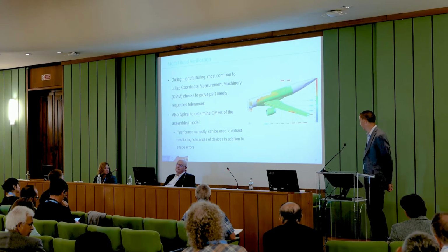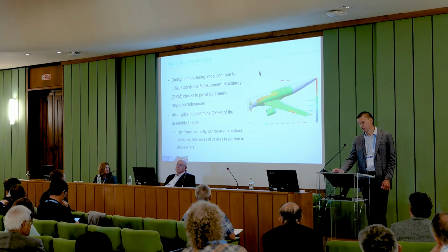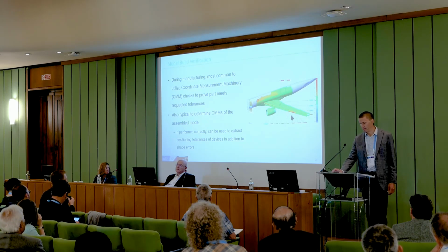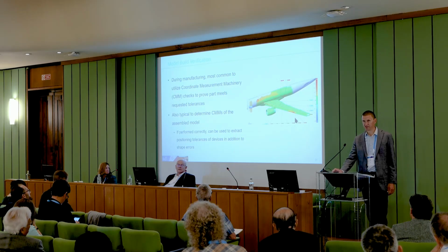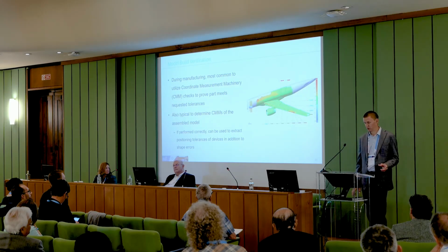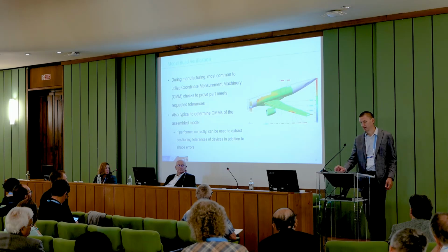This is an example of a CMM on one of the NASA builds. So again, you can see a lot of areas where the discrepancy is zero. You can see some areas where things start to light up. One particular slat looks to have some positioning error here. So this tells you a numerical value about how far out that is off from the reference surface, but it doesn't really give you what we actually care about, which is deflection, gap change, height change.